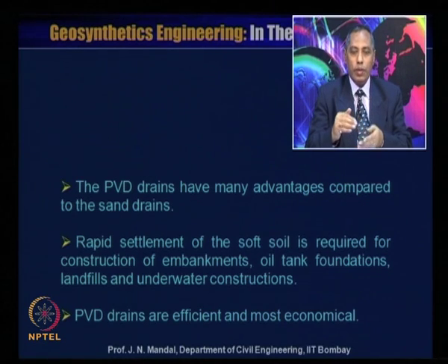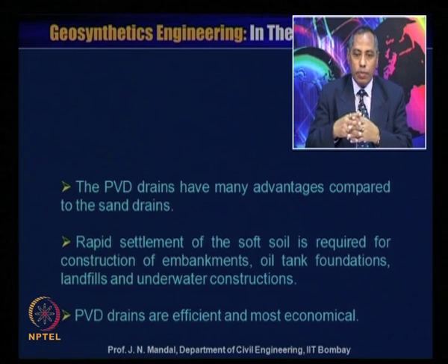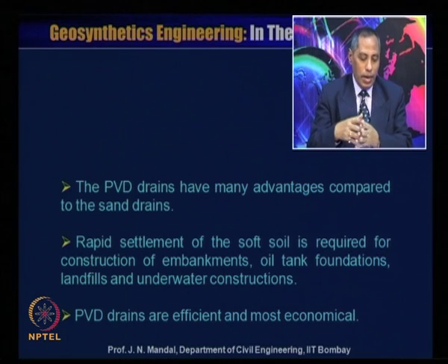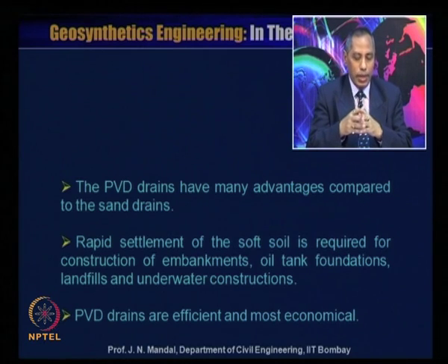So, you cannot put a heavy surcharge load, and also it is very difficult and critical to obtain the material for surcharge on the spot, and you may require about 10 meter height of the surcharge load, and that is very common.